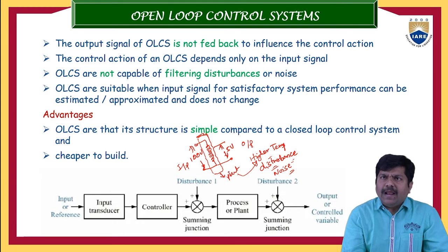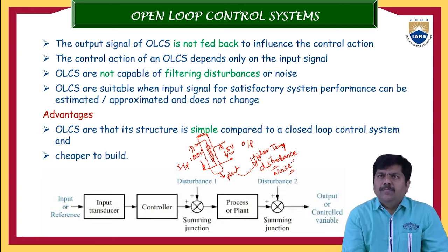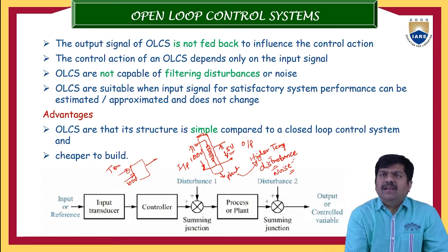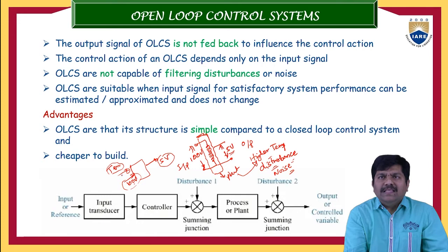Now, if this same plant is kept at a higher temperature, what happens? We may reach 5 volts or we may not. Indirectly, one input of this plant is the temperature variation, and the other is the 100 volt signal, producing finally this 5 volts. Whether we reach this 5 volts or not will be decided by two inputs, 100 volts and temperature. If the temperature is deviating or varying, then the temperature could be seen as an input by the plant.